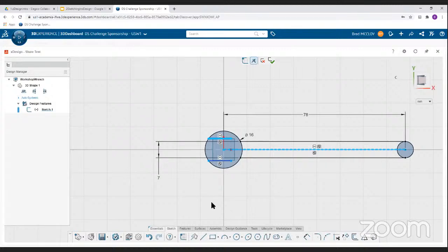And on the wrench, sticking a ruler in it, it looked like it was maybe about 9 millimeters deep. So I can click the sketch dimension toolbar again. I click that, and we can set it to 9. Now, some of the wrenches have a kind of hexagonal pattern here. Let's make an arc. So here, some of the elements, if you click on the dialog, there's different ways of making arcs. But let's try a 3-point arc for that one.